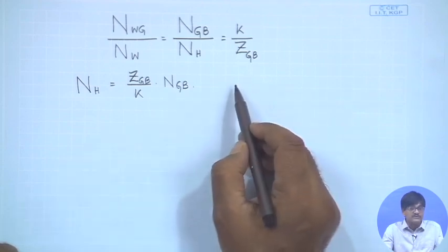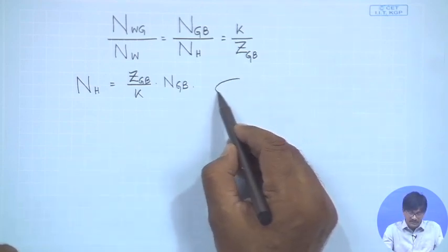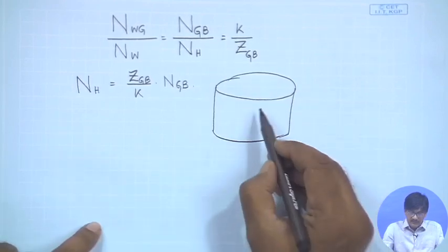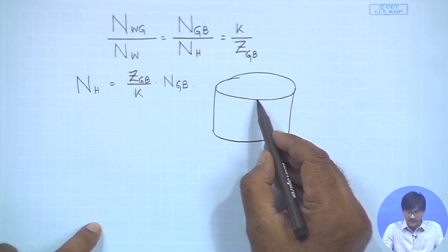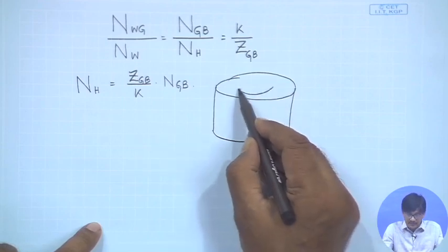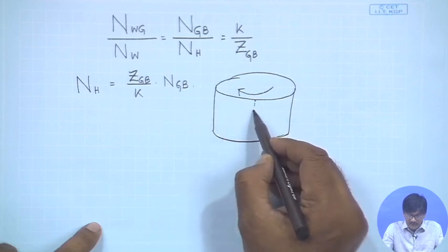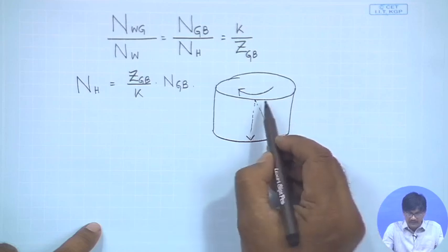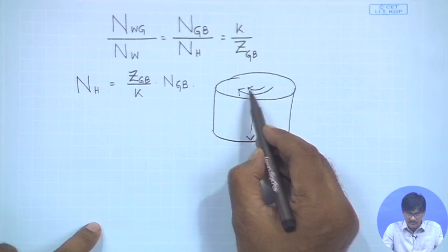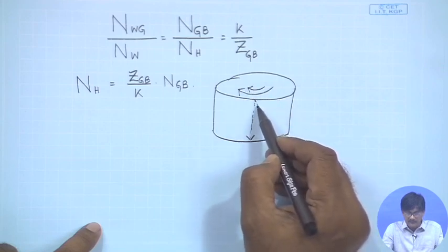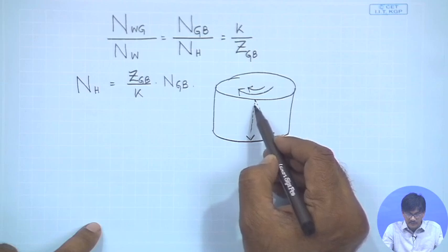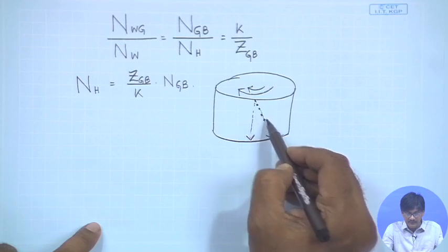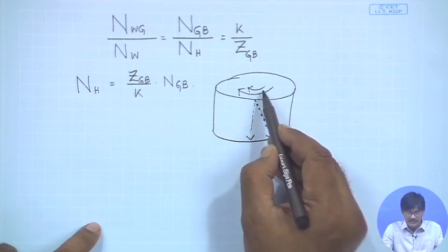But now the situation is changing. In order to cut a helical gear, we are deciding that every rotation has to have an additional rotation of the blank, so that the cutting will not proceed this way, but the cutting will be proceeding this way. We put some extra rotation of the blank, and that will lead the cutting action, the downward motion. The next point of cut will be here, next point of cut will be here, like that. What is this extra rotation?